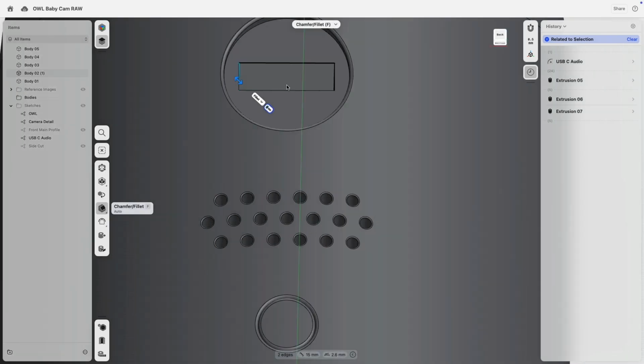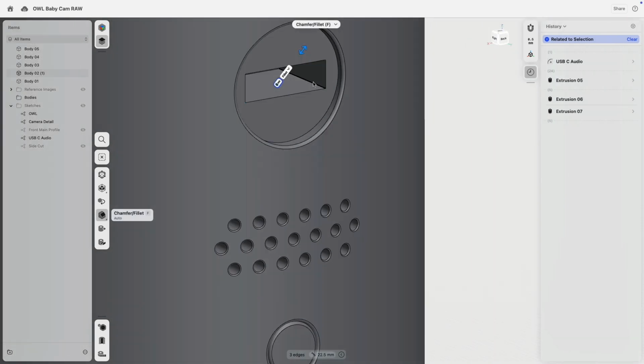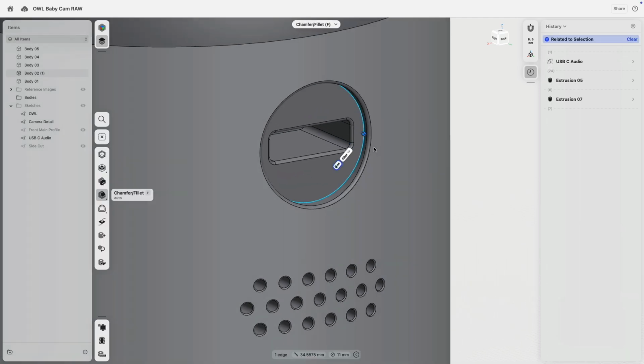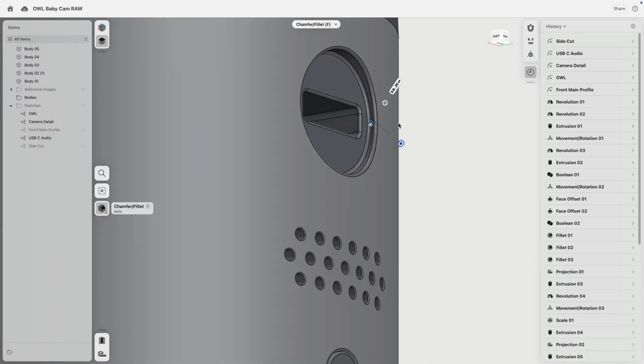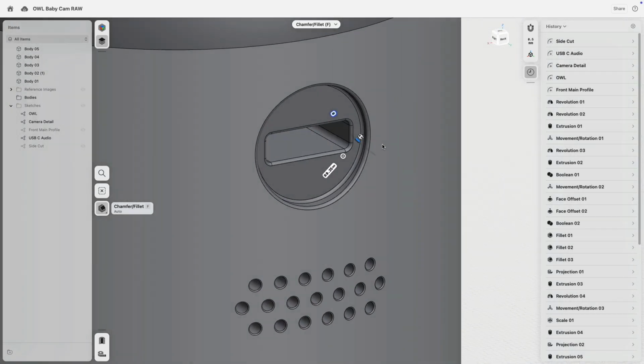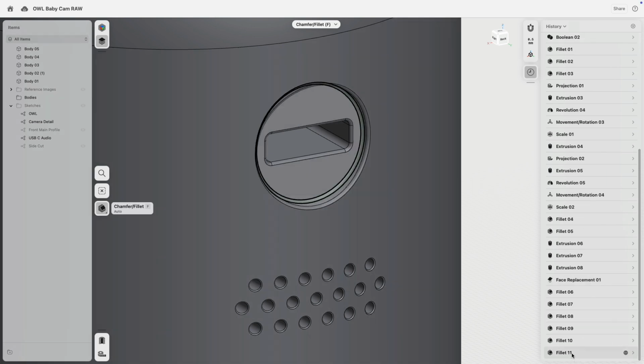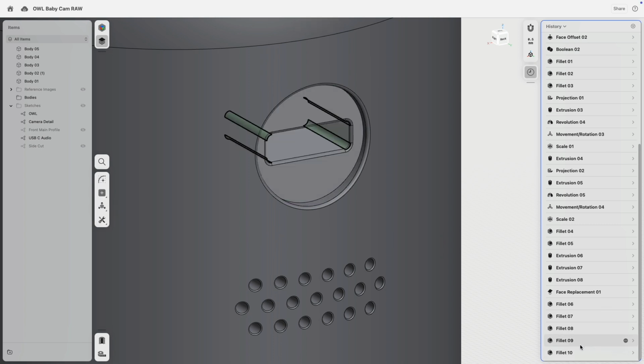This should be rounder, so I will select these edges first, and then I can round this. What about here? 0.25. Yeah, that all works. Okay. Because now I have 3 times 0.25 fillet, that's kind of a little bit insane, or simply not very effective.